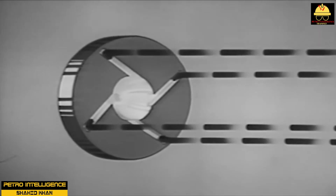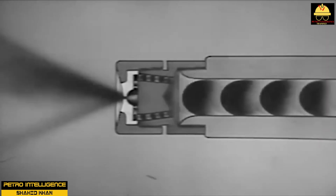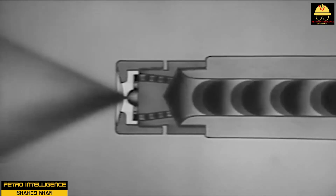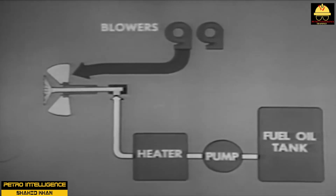The perfect mixing of air and fuel is impossible, and no practical way has been found to determine when the combustion process is complete. Incomplete combustion indicates that unburned vapors will be present in the hot combustion gases. To be on the safe side, most facilities use excess air to ensure all of the fuel has been burned.